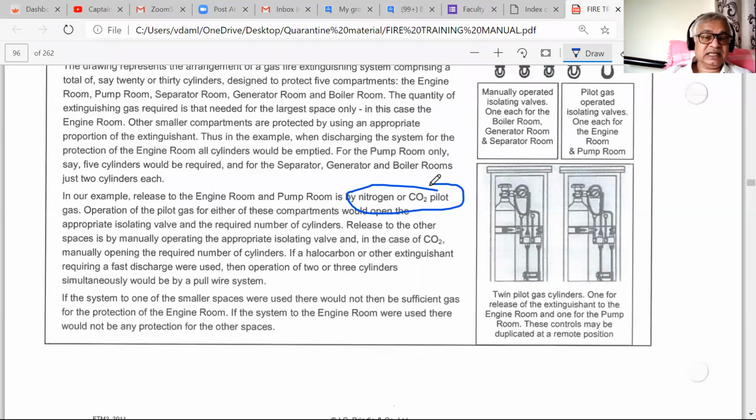When the gas is released, there is another problem: CO2 will be at extremely cold temperature and may form dry ice. If dry ice is formed on the tips of the nozzles where you are releasing the gas, there is a risk of static electricity buildup and a spark.